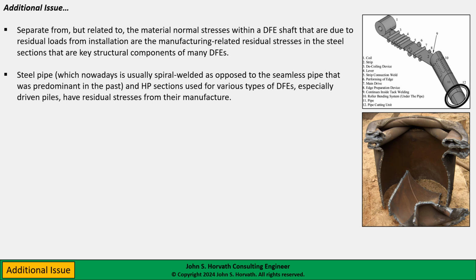So this is a classic case of a good weld, if you will, where the strength of the weld is stronger than the parent material on either side. So although the steel yielded, the welds did not separate. And I emphasize that because, as I said, that was the bad rap that spiral welded pipe had many decades ago, that the welds were not as high quality and that you could drive a pile and just have this thing unspiral before your eyes.